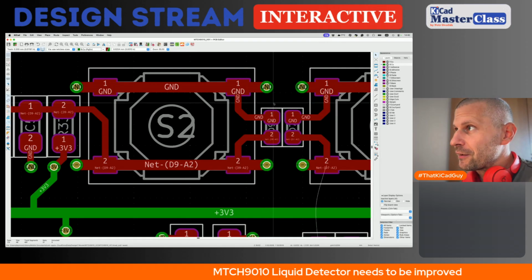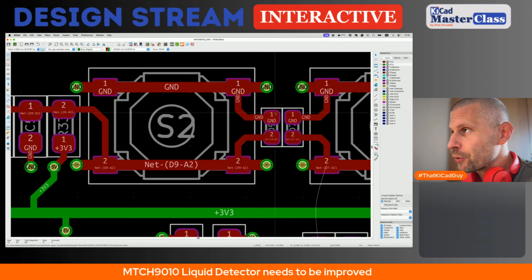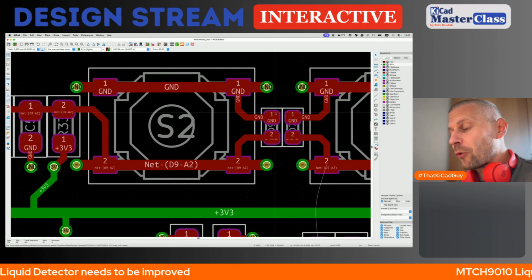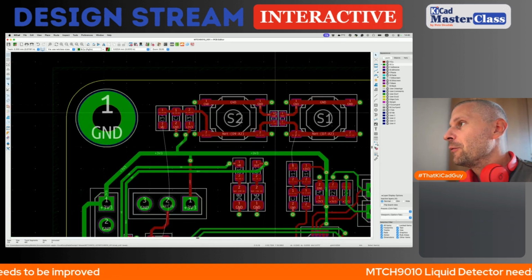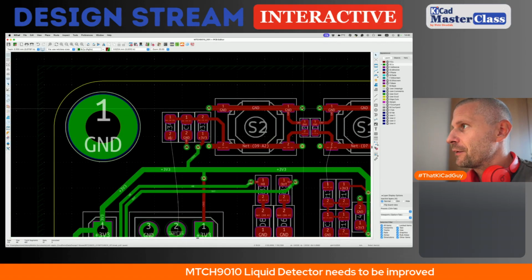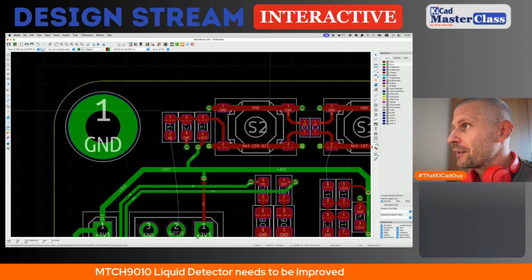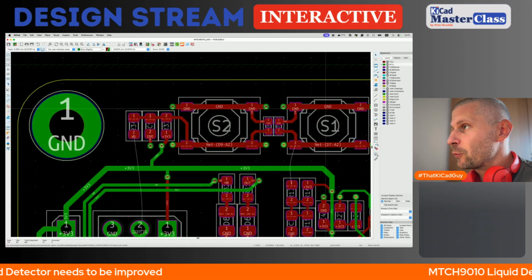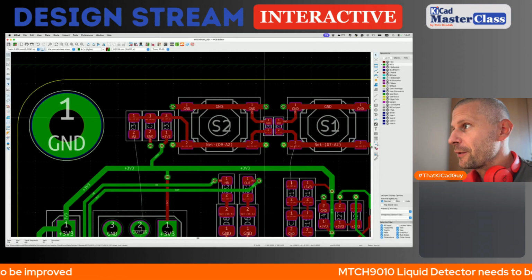And ideally, the via should be here to shorten the distance the energy must travel. But I like the symmetrical design, and the fact that these two lines are firmly connected to the ground. I will do it this way.